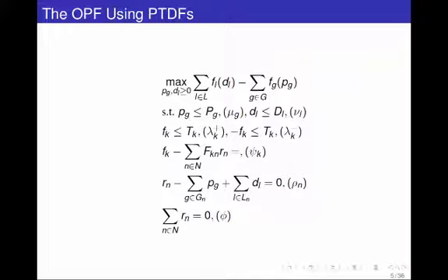So suppose in this example that the limit of power that a line can carry is 100, and the flow is 90, so we're sending 90 megawatts from 1 to 2. I go from 100 to 101, and I resolve the problem. Is there any chance I'm going to get a different answer about what the optimal solution is?